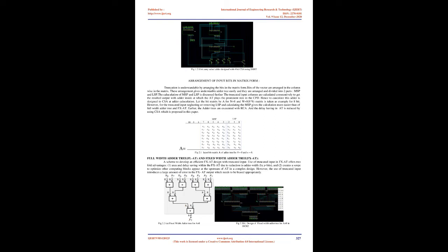Carry select adder contains multiplexers and adders. Giving source voltage and ground to the 2-bit adders saves time separately. The selection line for all the multiplexers is the one resulting carry, which decides the other carry input. This operation of the carry select adder leads to lower delay in the hardware. Hence, to achieve lower delay, RCA in the adder trees is replaced with carry select adder, which is the main idea of the proposed paper.